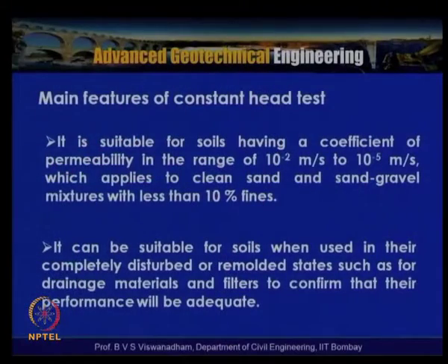The main features of the constant head test include that it is suitable for soils having a coefficient of permeability in the range of 10 to the power of -2 to 10 to the power of -5 meter per second, which applies to clean sand and sand gravel mixtures with less than 10% fines. It can be suitable for soils when used in their completely disturbed or remolded states, such as for drainage materials and filters, to confirm that their performance will be adequate.